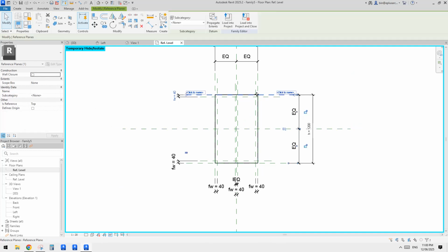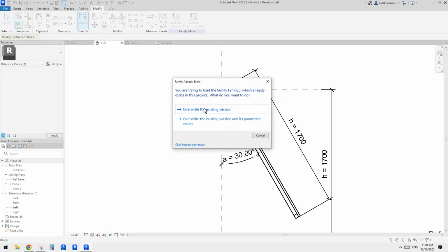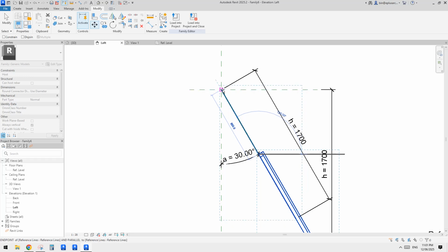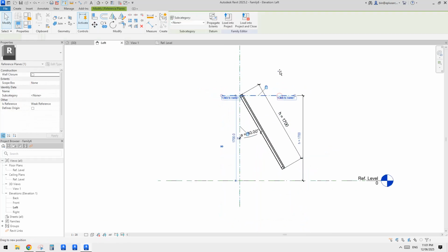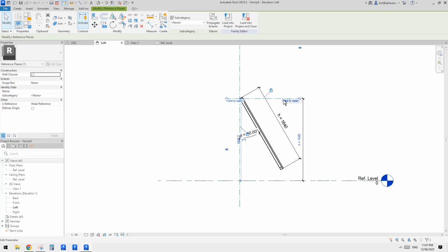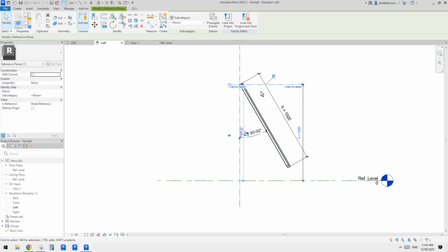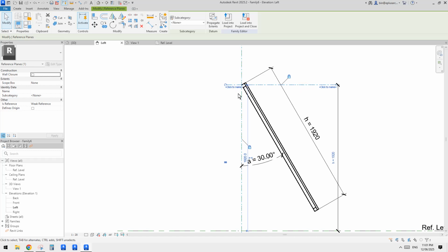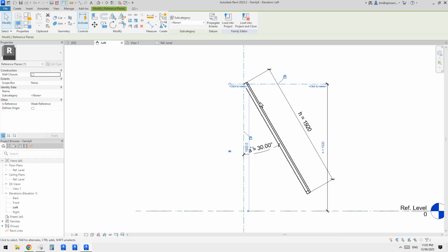Because we want the top of this panel to be the origin, to be the base point, we can just tick this box and then load this back in here, override. And now we just need to move this to here. So now you will see it will stay here, stay at this point. So we don't need that 0 dimension to lock this panel anymore.